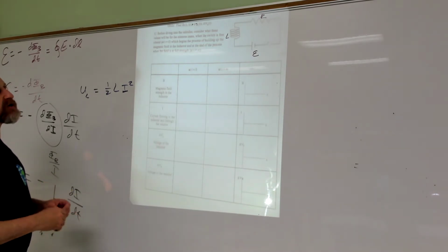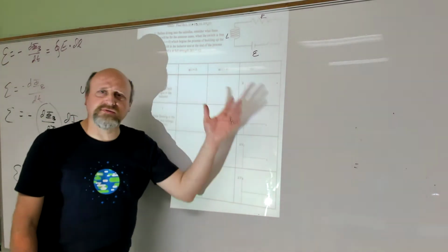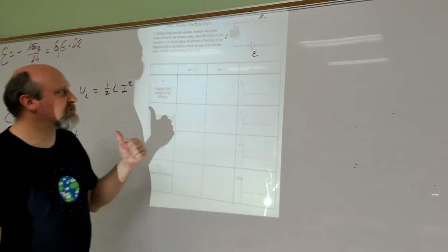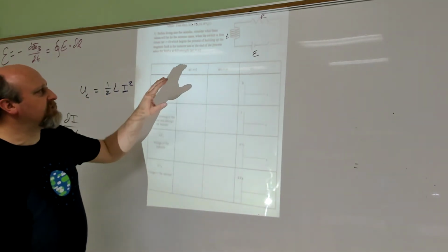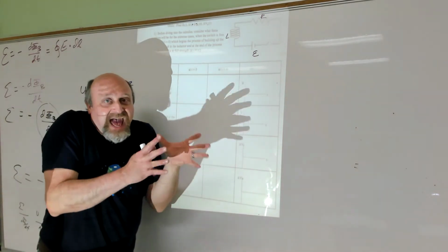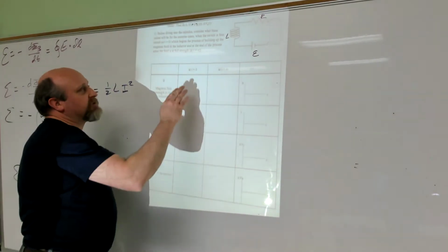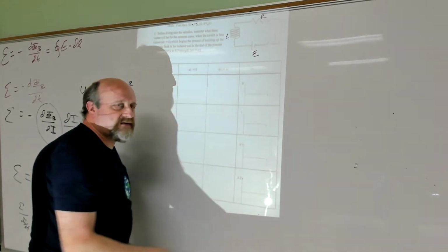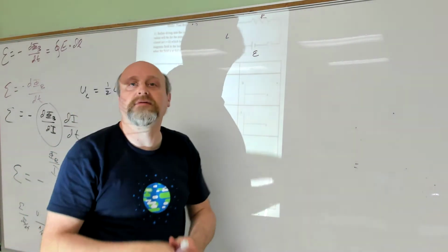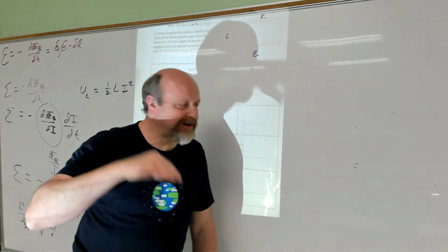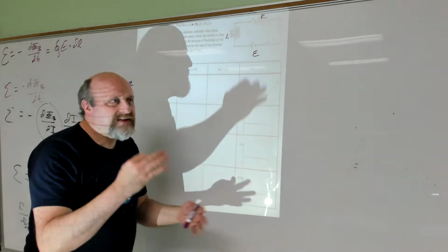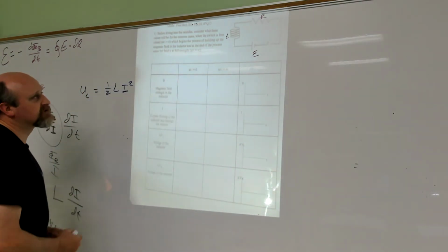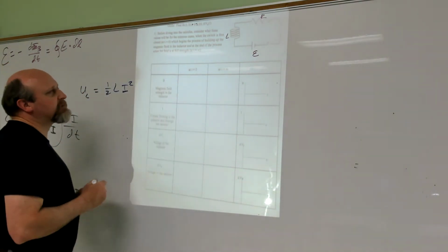All right, so this is kind of like doing the RC circuit stuff with resistors and capacitors in circuits. If you can think about what's going to happen and figure out what the values are at time 0 and the values at infinity, and sketch out the graph of how it gets there, that's usually like 75 to 90% of the points on a problem like this. So here we go. Let's think about what happens at the start.